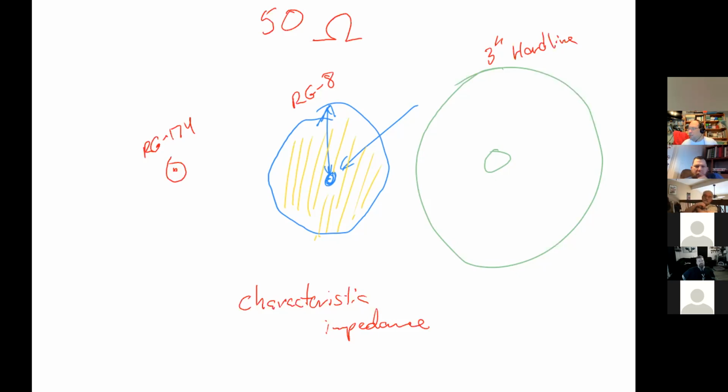Signal loss. And why signal loss? Well, if you've got a long line, you don't want a lot of signal loss. Right, but what makes it have signal loss? Resistance. That's right. And which wire is going to have a higher resistance? The smaller wire. That's right. So this cable is going to have high loss, and this one is going to have very low loss.